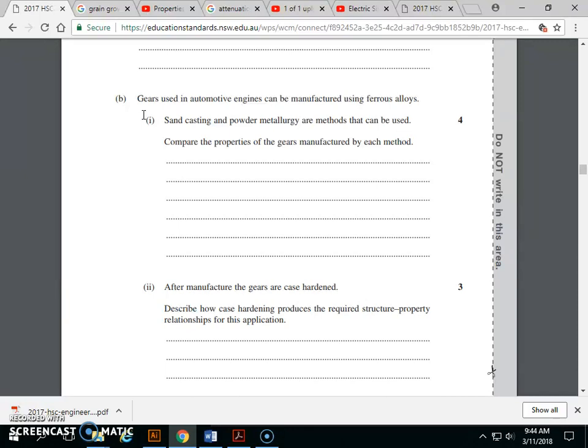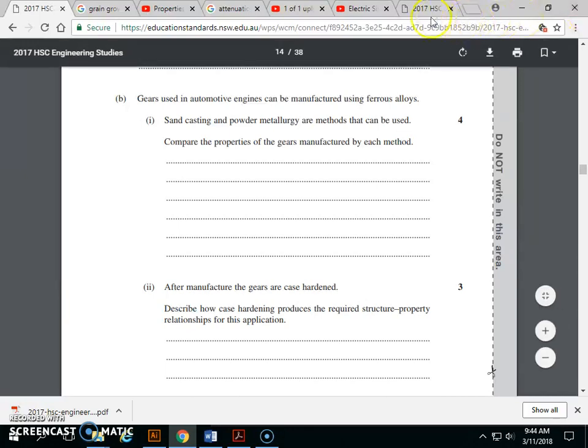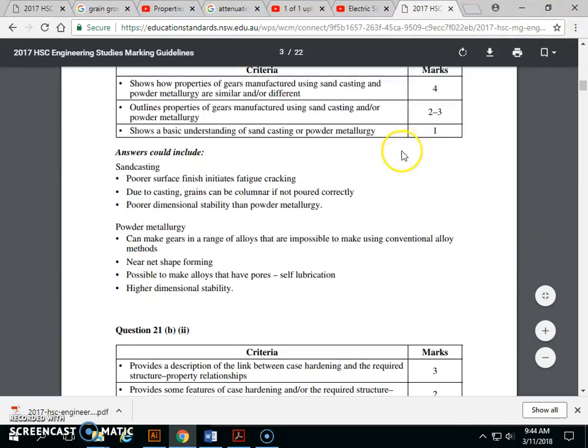Whereas on the other hand, when we're dealing with cars, we've got large loads, and we need things that are tough and aren't going to fall apart. There are other advantages of using sintered metals. Those sintered metals are typically cheap for the amount of accuracy that they give you. They don't need to be machined. They can be lubricated very easily because they're porous, so we can have self-lubricating equipment. But that's enough, I think, for an answer. But let's see what they say before I go on and say too much.